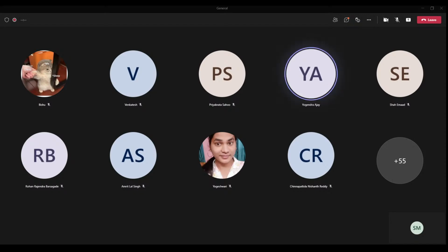But if you tune the potentiometer in some other way, then for the same IR radiation, you can get a low. So it all depends on the comparator circuit, and based on the environment you are in, you need to set the potentiometer accordingly. But the IR sensor which we provided you is pretty good and works in indoor environments.